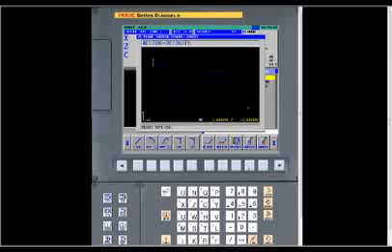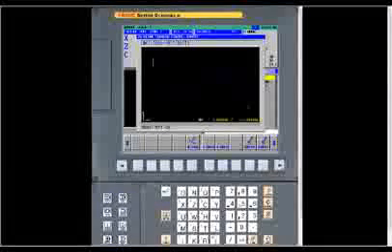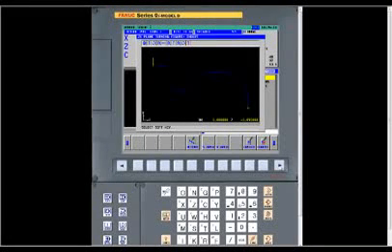But now with Manual Guide I, it's very critical that it has to be a closed figure. So at this point, if you press the right shift key, this key, the right arrow key, 4 times, 1, 2, 3, 4, we went through a bunch of fields there. At some point in our next sequence, we'll go over all of those individually, but we don't really have time to go through them all today.